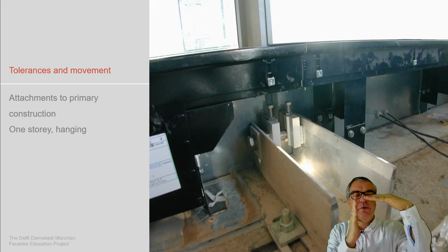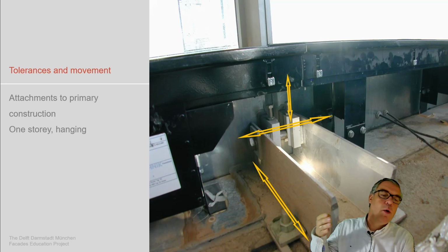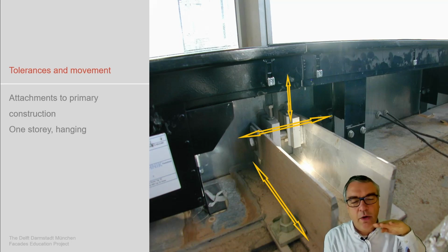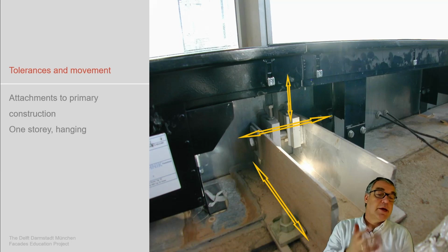So somewhere there's a concrete and the facade, which is quite precise, that needs to be adjusted in all 3 directions. And that's what these details do. They allow a horizontal and a vertical positioning in this direction, and they allow a horizontal positioning in this direction as well.